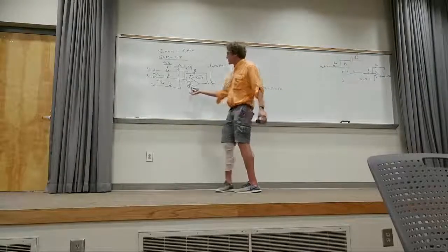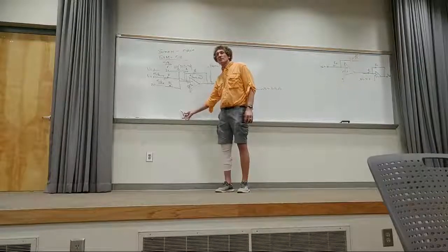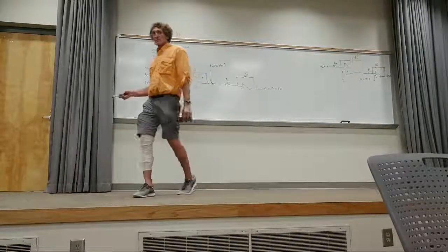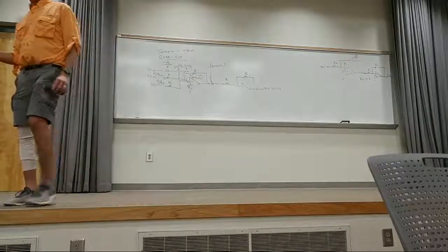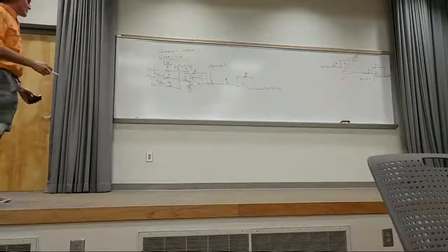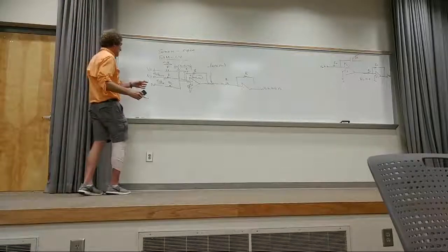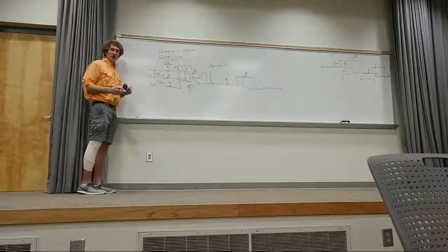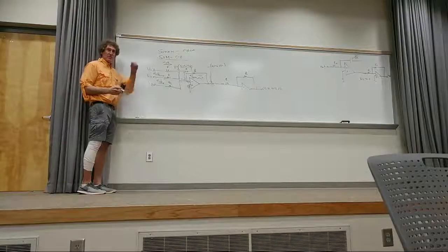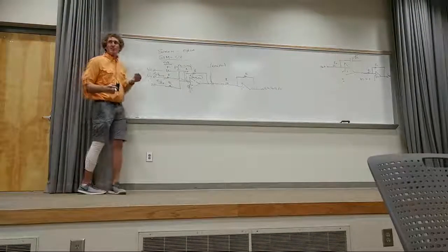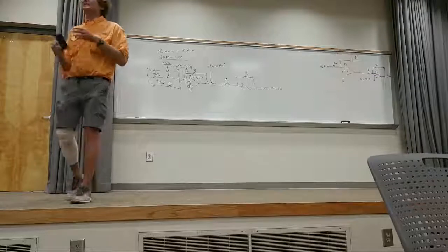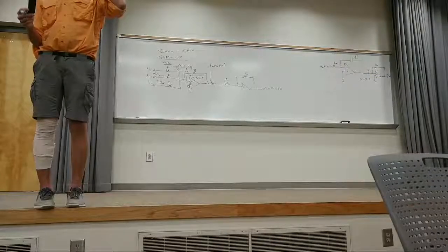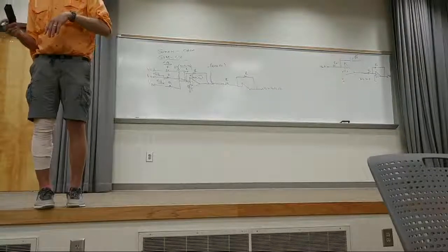And how many of you can see you could extend this to any number of input voltages? Can you all see that, class? And therefore, I can sum the circuits, right? And if you wanted to subtract one of these values, then you could put it through an inverter before you added to that, and it would subtract it. Do you see that, class? So now we have the basic building blocks to realize any type of polynomials in S. We can build the circuitry that will do this.